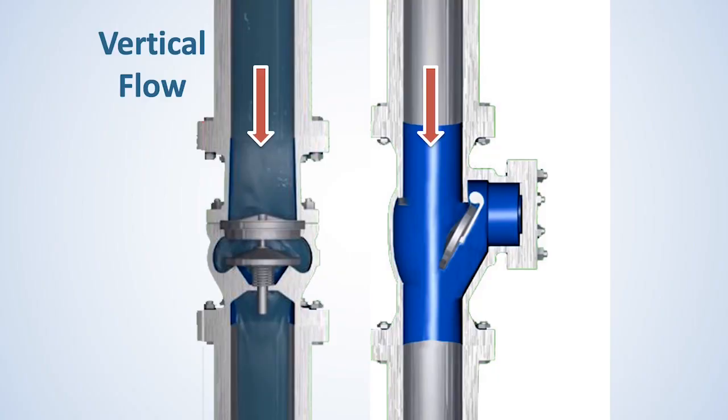This slide builds on the previous slide that you were just looking at and illustrates some of the problems associated with vertical pipelines. The flow direction, of course, compounds the issues that need to be considered. If normal flow is up, then the axial flow check valve has to have a slightly stronger spring to compensate for the weight of the disc and the stem. This stronger spring will keep the cracking pressure within the range of a nominal 1/2 psi, which is desirable for most applications, whether it's a vertical line or a horizontal line.